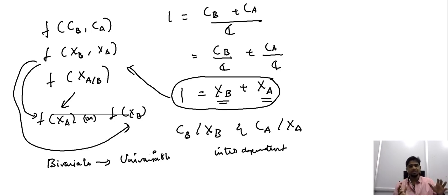Generally, when you are considering a binary system, you have to largely focus on a bivariate function. But through our focus on a specific form of a system, we were able to describe the free energy of a binary closed system using a single variable alone. This single variable can be either the mole fraction of the alloying element or the mole fraction of the base metal, irrespective of which.